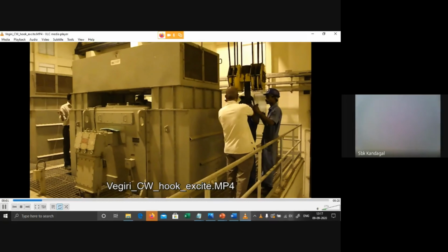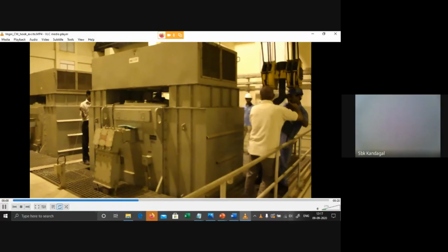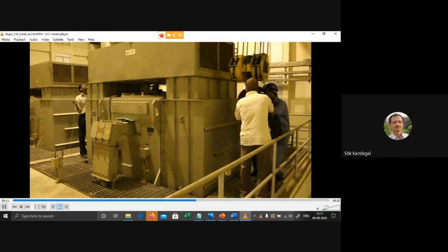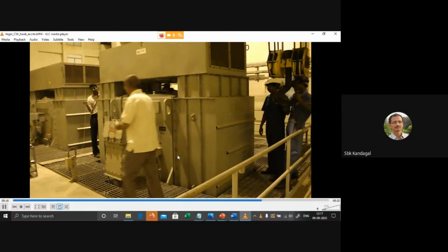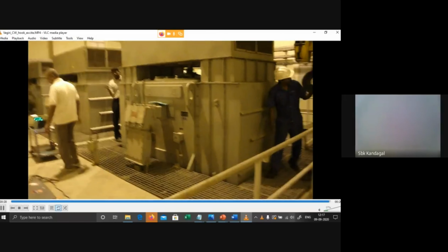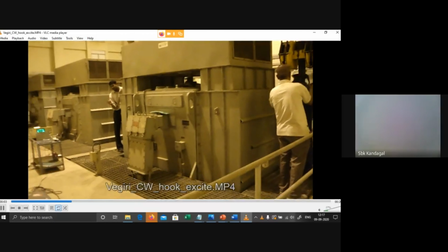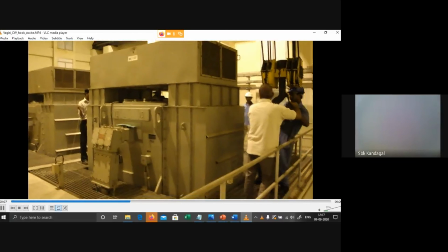Now what you are seeing is a motor system above the floor, on a trapezoidal support on top of it. So you excite the structure with it. Now you can just see that. Okay, now the pulse is given, and that pulse itself is used, both in the x and y direction. So now you can just see that again. Now in the flow direction, the x direction, the natural frequency is found, and similarly in the y direction it will also be found.